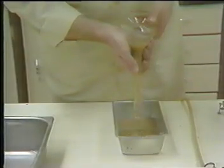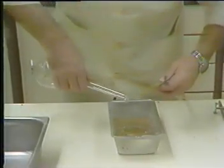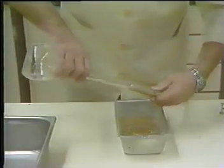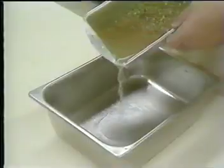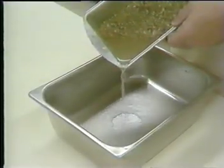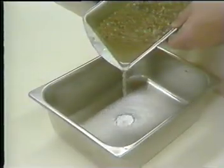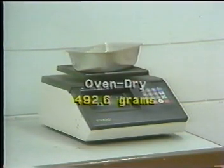Remove the fine aggregate from the flask by pouring it into a suitable size container, making sure to remove all of the test sample by rinsing with additional water if necessary. Carefully pour off the excess water to avoid loss of fines and dry the sample to constant weight at a temperature of 230 degrees Fahrenheit plus or minus 9 degrees. Cool it in air at room temperature for 1/2 hour to 1½ hours and weigh it to the nearest 1/10 of a gram. The weight of our test sample, oven dry, is 492.6 grams.